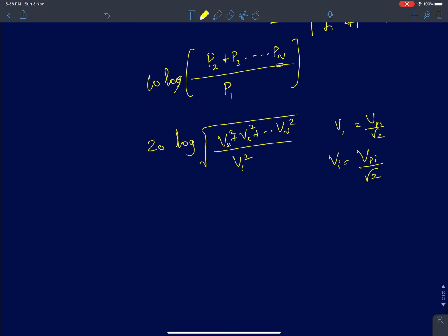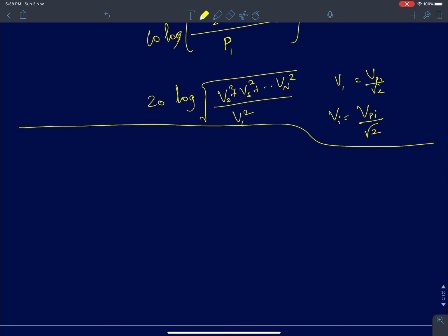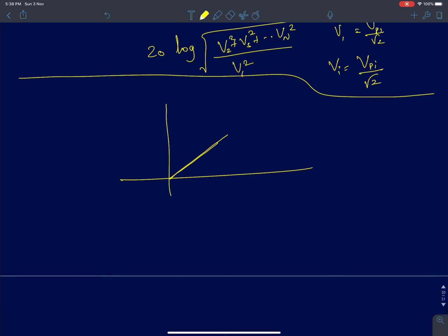And we said THD was a sufficient metric when we discussed low frequency circuits, but that's no longer the case when we talk about RF circuits, radio frequency circuits. So to characterize that, one of the first parameters we discussed was gain compression. We said that as you keep increasing the input signal, your gain starts to droop. And we also discussed two important nonlinearity functions. How do you characterize an amplifier? We said we can model an amplifier as a compressive nonlinearity.